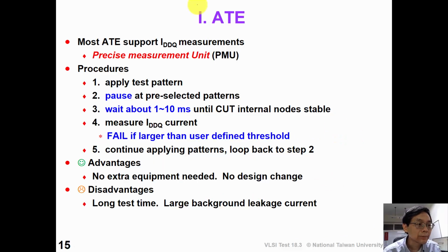For the first method, ATE measurement, we can use a precision measurement unit, or PMU, to measure IDDQ current directly. The procedure is like this.